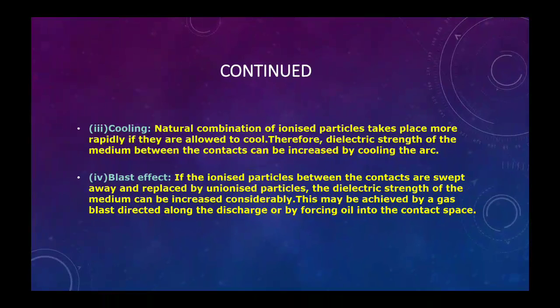This may be achieved by a gas blast directed along the discharge, or by forcing oil into the contact space with the help of a forced oil circulating system, as in the minimum oil circuit breaker or bulk oil circuit breaker.